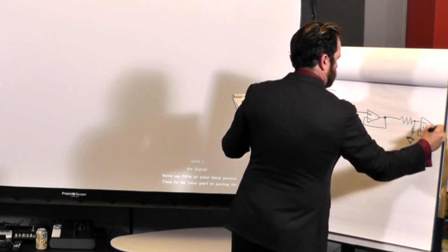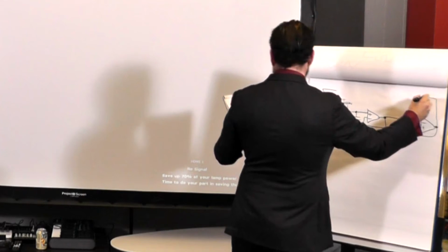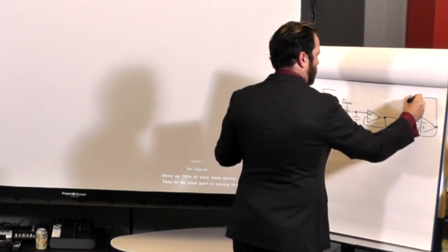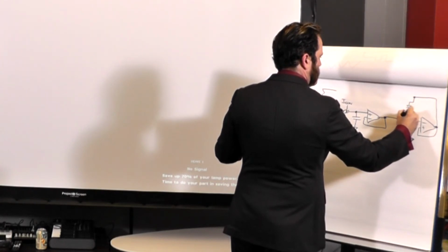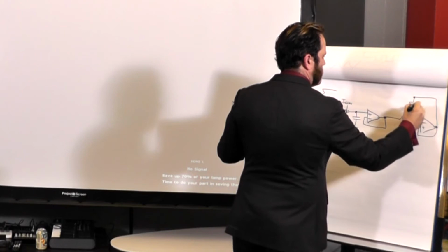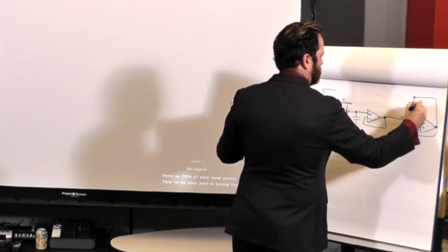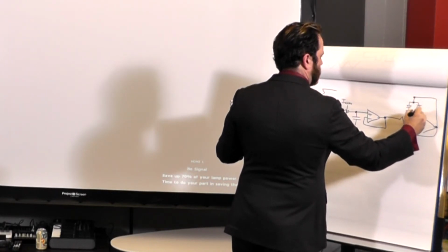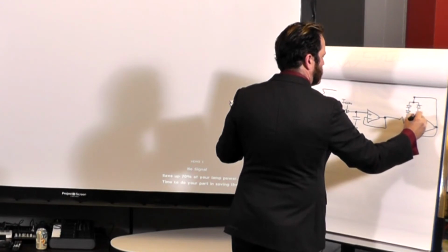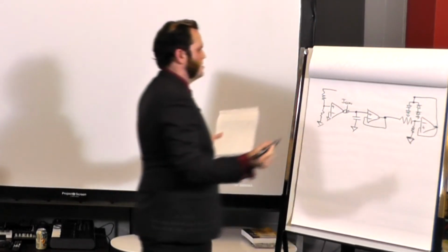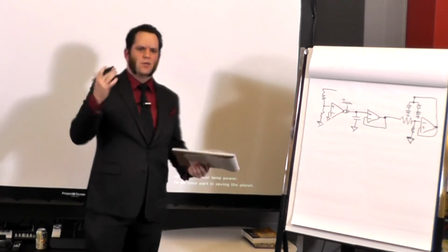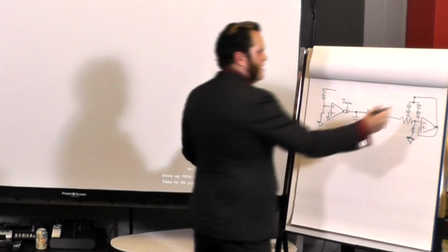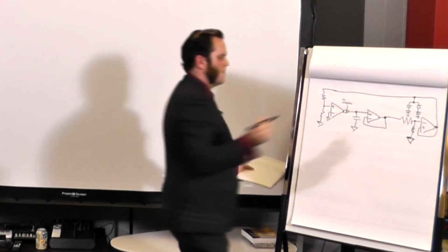All right, this is a thing there, and then I'm going to clamp that with some diodes. Hey, look at that. It's like I can draw or something. I can't draw. Don't let me draw. It's a bad idea. So that diode clampy thing keeps that to plus or minus 1.4 volts. And this is then coming back this way.